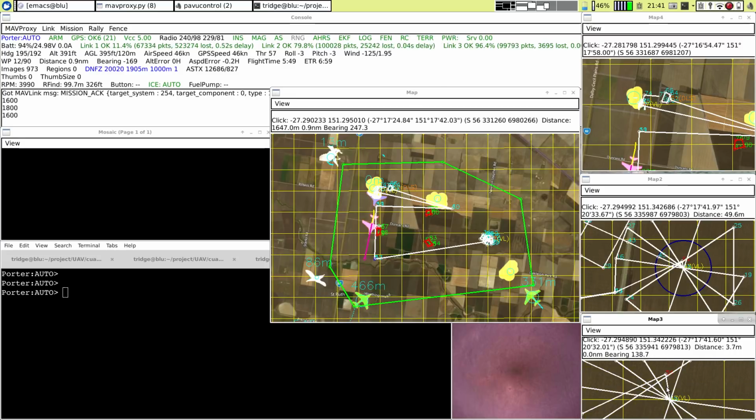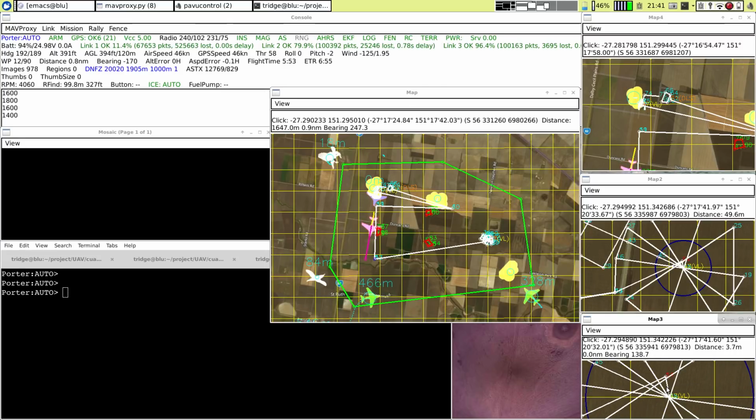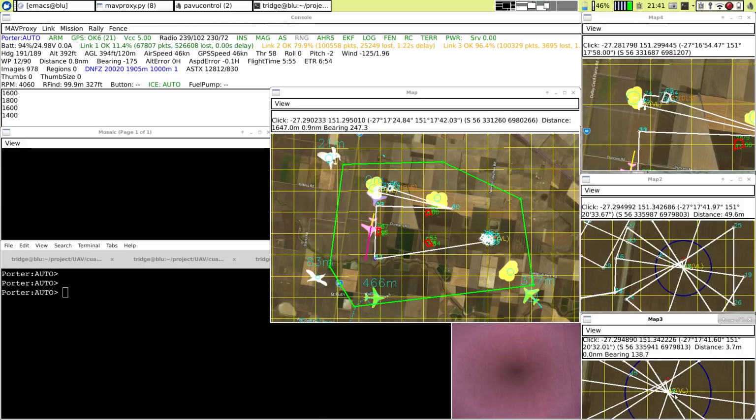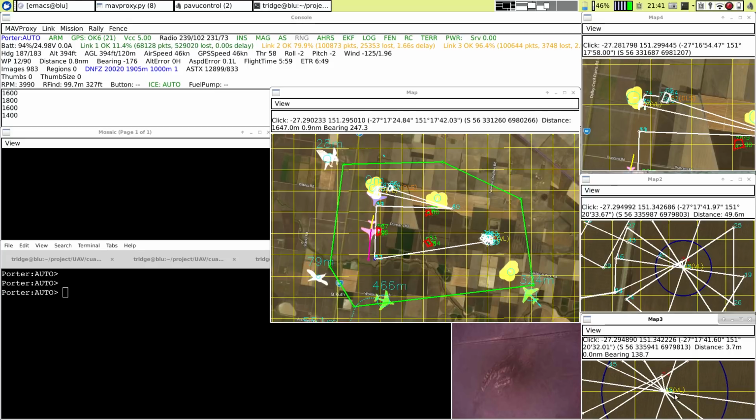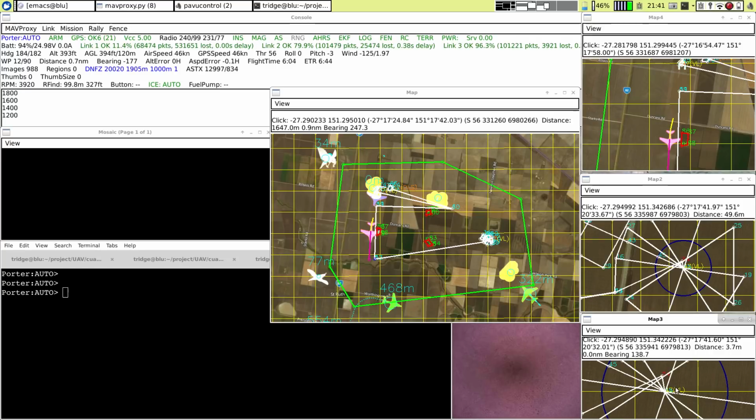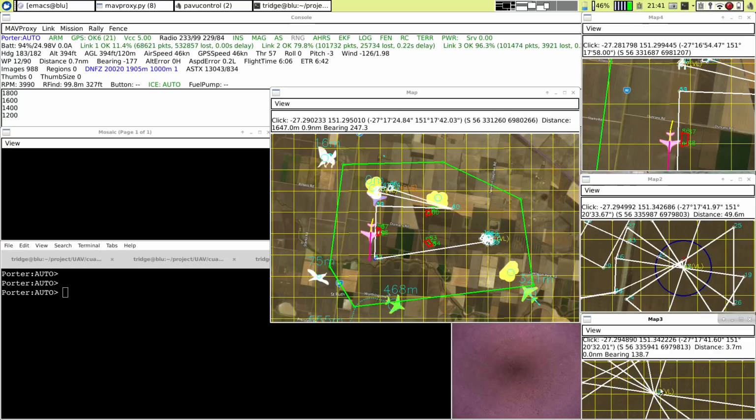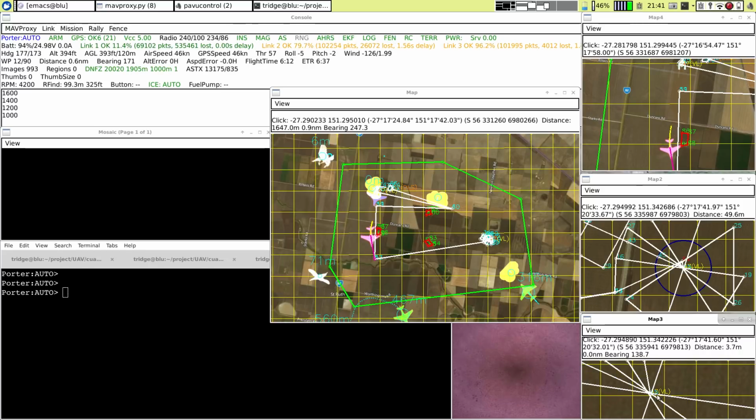There's a red and blue target that the farmer who's in trouble has put out for us, and our aircraft will automatically find that target and geolocate it and then choose a landing location and land. We then have a zoomed in map here which will automatically be zoomed in down to just a few meters around the landing zone, so we can see a really close in view of what the images look like of the target near the landing zone.